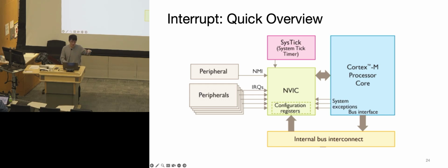Of course, like we said before, there are different types of interrupts, like the system interrupts, system exceptions, etc. They come from the cores, and we also have what they call the system tick timer, which is a specialized timer built into the Cortex-M processor. It's a simple and effective way to do periodic interrupts, such as delays or system timing. We're not going to talk too much on that, but it's just in case you're wondering.